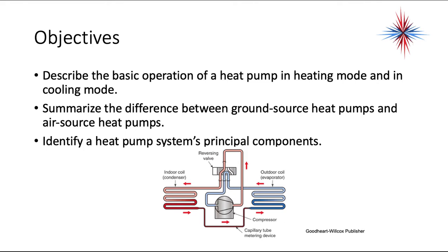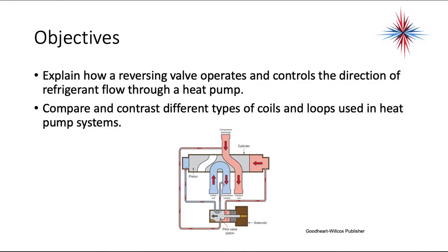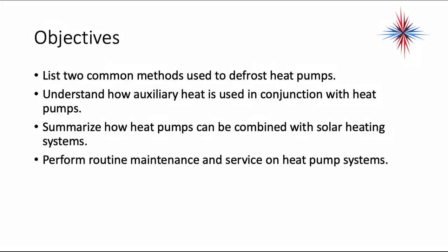We want to summarize the difference between ground source heat pumps and air source heat pumps. We want to identify heat pumps' principal components. We want to explain how a reversing valve operates and controls the direction of refrigerant flow through a heat pump. We want to compare and contrast different types of coils and loops used in heat pump systems. We want to be able to list two common methods used to defrost heat pumps.